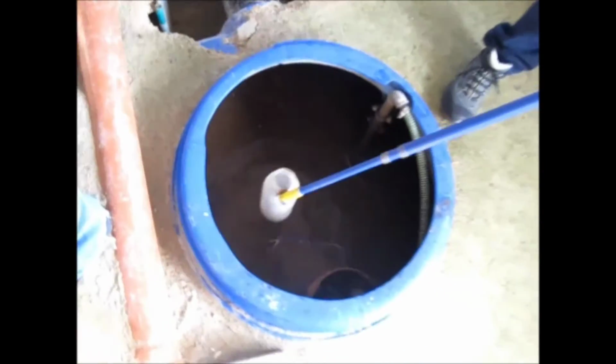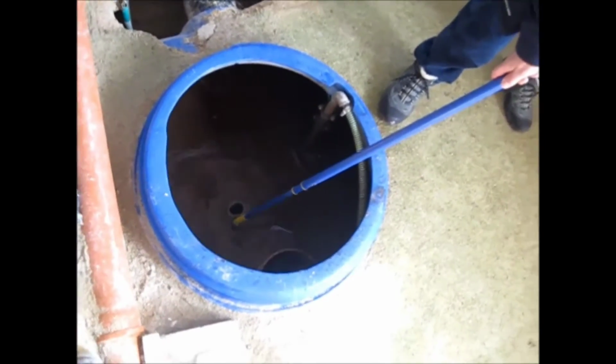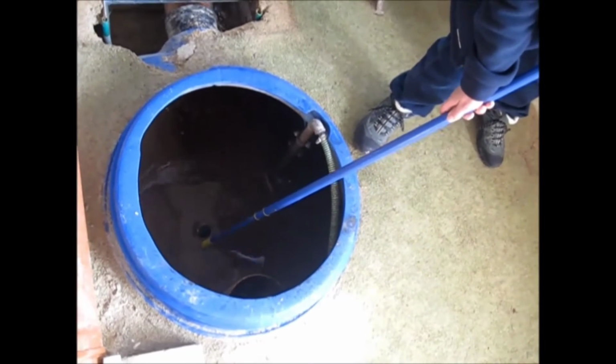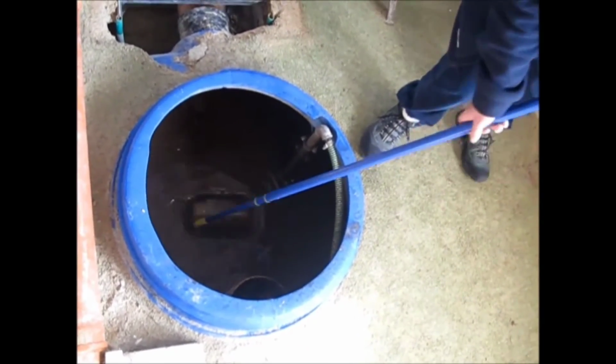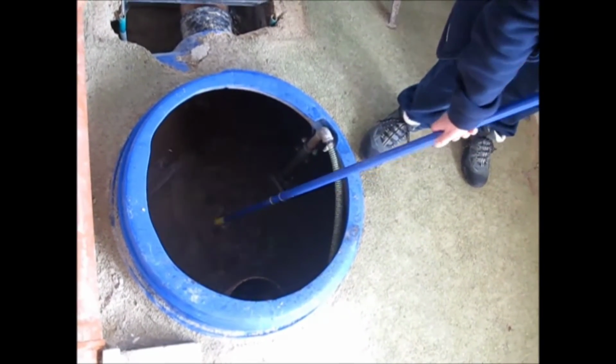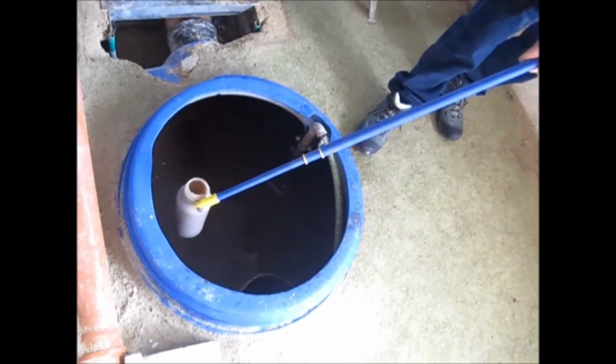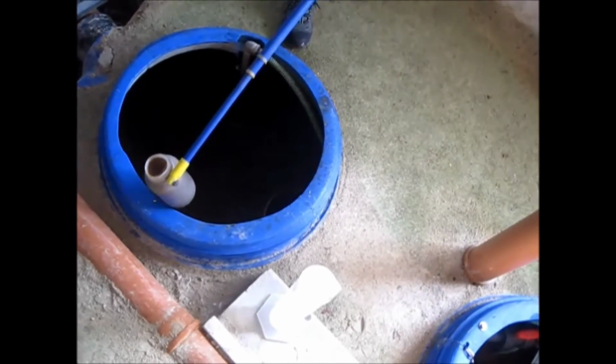You can see the wastewater flowing into the plant. The first reactor contains a high concentration of microorganisms, which can be seen in the brownish sludge. This reactor, the first one, is driven with a very low content of oxygen. So denitrification and phosphorus removal can take place here. Here you can see the brownish wastewater, which is actually the microorganisms that you can see.